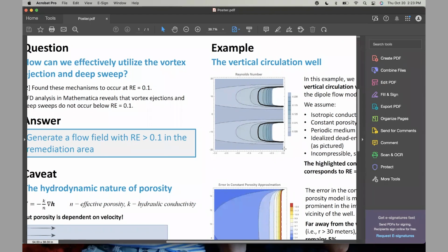So we can start to say, well, it looks like we have a lot of small crevices or small cavities that are on the same order of magnitude as our through channels. That's an important distinction you can start to make. And then you can say, is it washed? Are they rounded? Is it unwashed? Are they jagged? Do they look like triangles? So you'd have to do some sort of analysis on your media to really make a more accurate approximation of what's happening in the pore space.